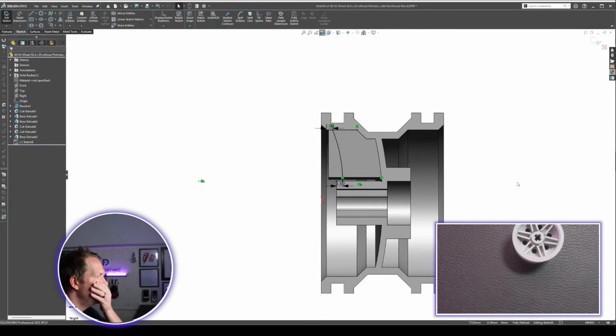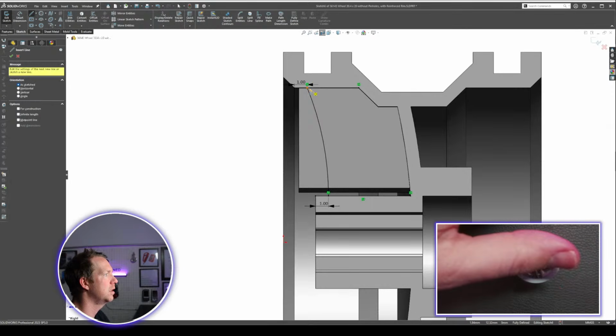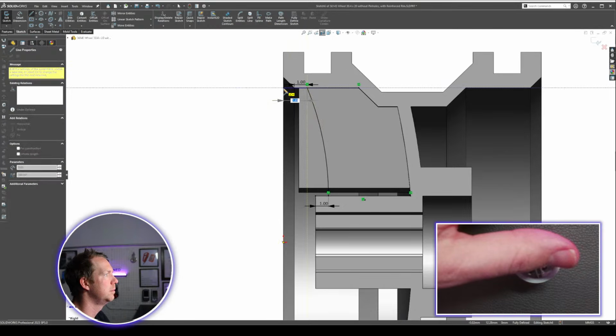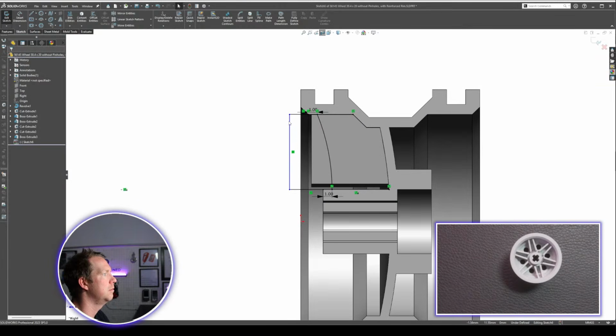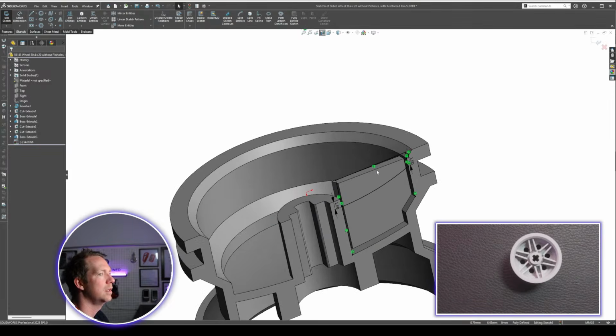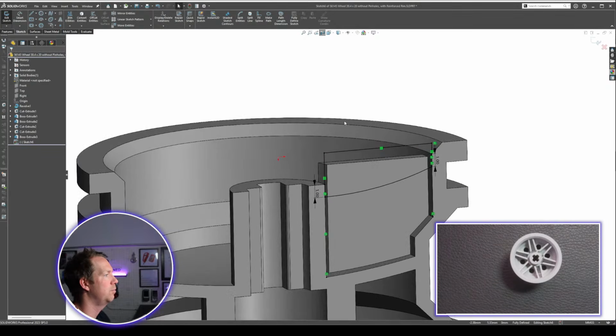All right. That is that. We can cut revolve to get the top edge off. I'm just going to close it up. To do that, I'm just going to add some more geometry. Can just bring it in here to get it fully defined. All right, so that's what we're adding. That's the profile we're going to cut.